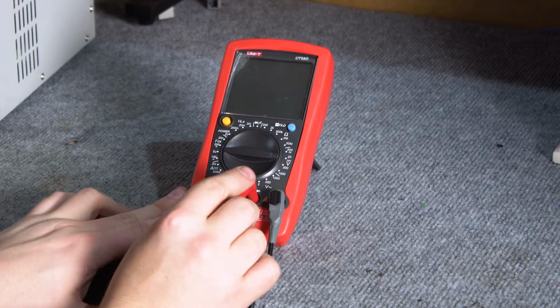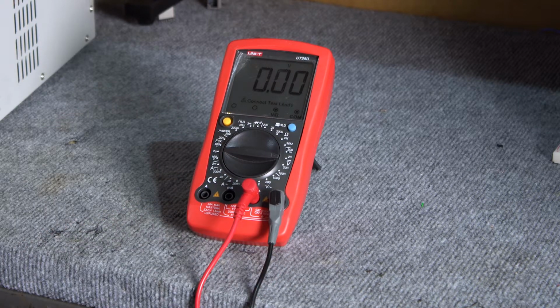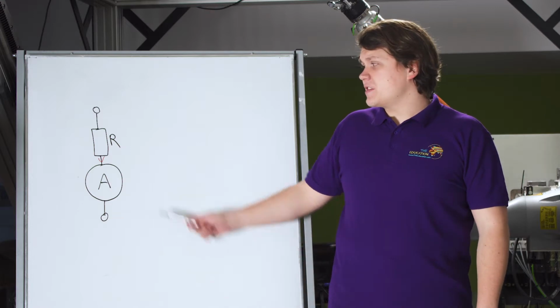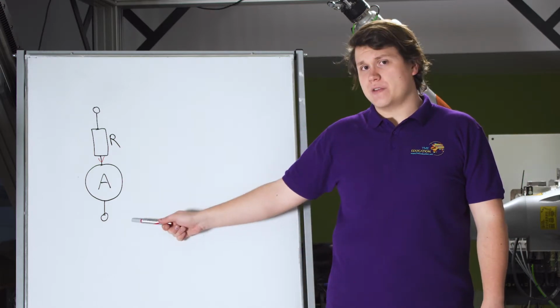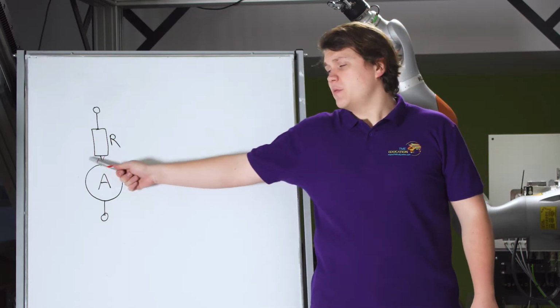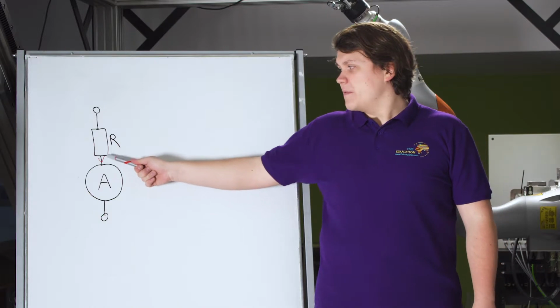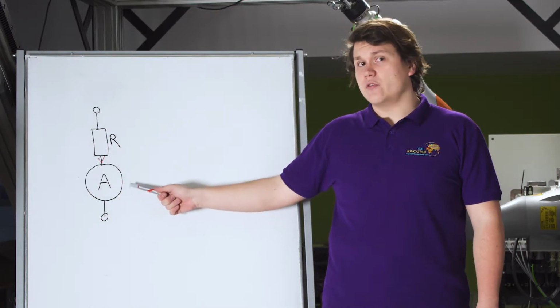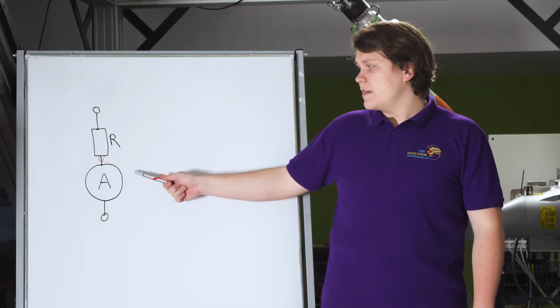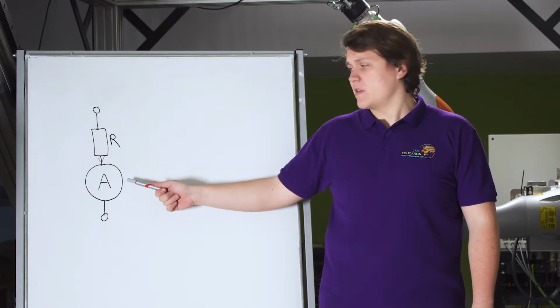When measuring the voltage, if we made a mistake and the probe would be in a terminal for current measurement, we could damage the system by shorting. The ammeter measures the current flowing through it. From Kirchhoff's first law, we know that it should be plugged in series in our circuit. So before plugging in our ammeter, we have to disconnect the circuit. The meter should have the lowest possible resistance to cause the lowest possible voltage drop.